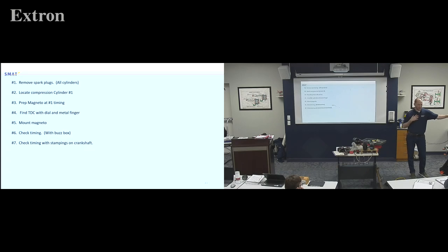I like the easy way, that's foolproof. The instruction manual might have you go all the way right now. If it says 80, I could do some math and figure out where top center is going to be. But the easiest way to do this is to say, I'm going to go 80, take half of it towards top center. If you notice, I got bottom center and top center, only one direction's towards top center. So it says 80, I'm going to go halfway, which is 40.